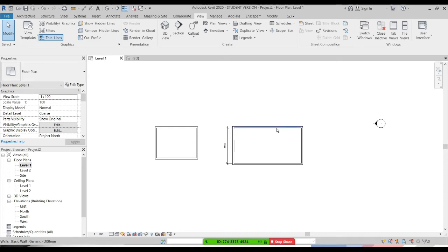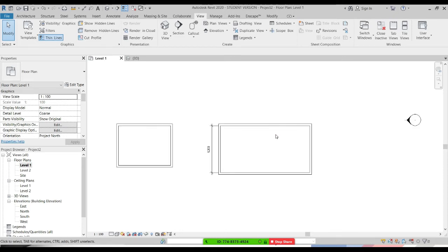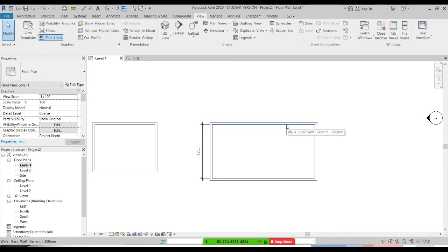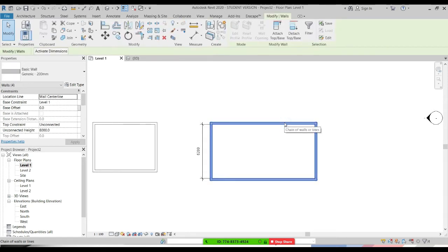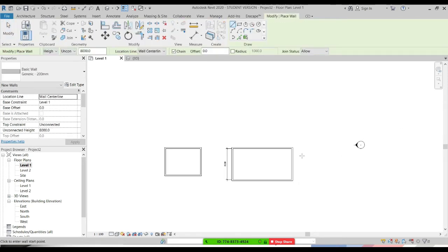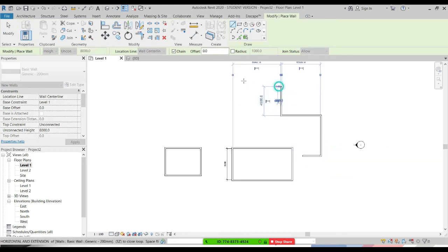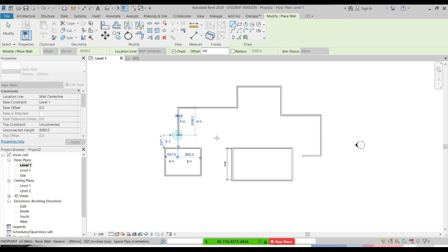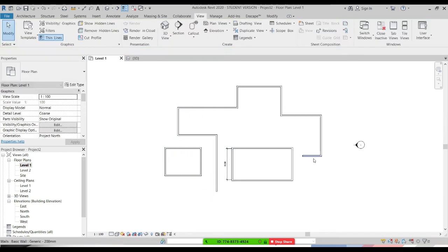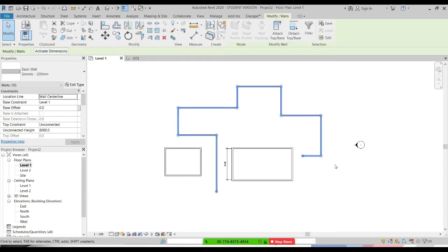You're welcome. If you want to select connected walls like these, there is another option that you can use, which is Tab. Just move your mouse near that wall, click Tab once, don't hold it, and then you can select all these walls. This makes it easier to select any number of walls, as long as they are connected. I can just click Tab and then click with my mouse to select it. This is another way of selection. Now I can change it again to level 2.